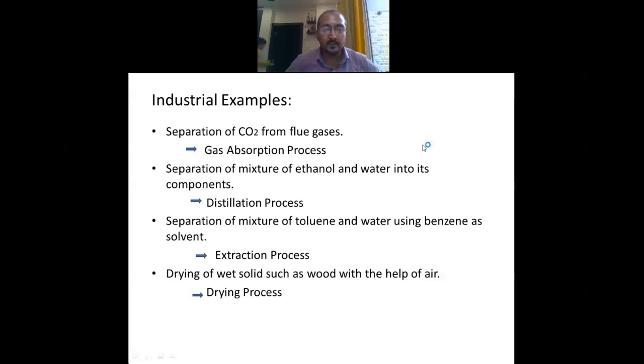We have two phases. Like in gas absorption, we have a gas mixture and we are using a liquid solvent, so we have a gas liquid phase. In distillation, we are separating the liquid solution and creating another phase, a vapor phase, by adding energy. So again we have gas and liquid phases. In extraction, we have a toluene and water solution, which is a liquid phase, and we add another solvent, also liquid but immiscible, so we have two immiscible liquid phases. In drying, we have a solid and air, two phases.